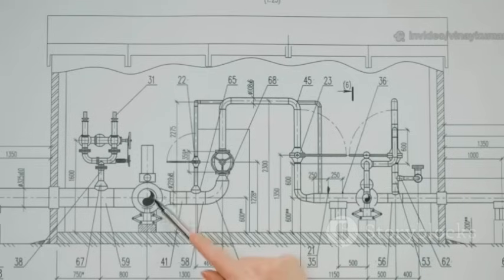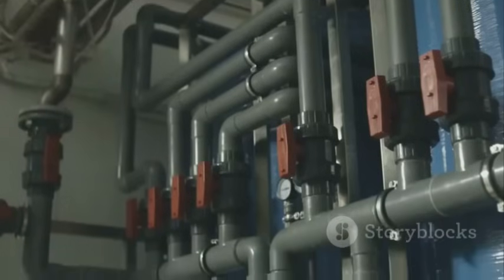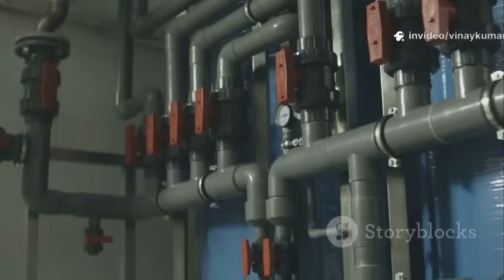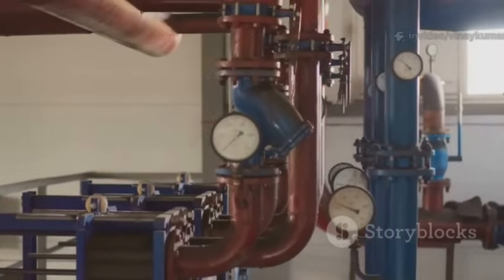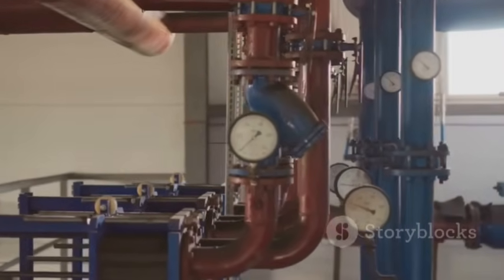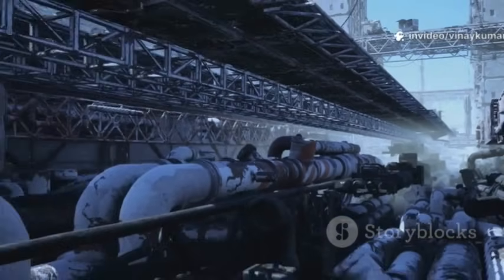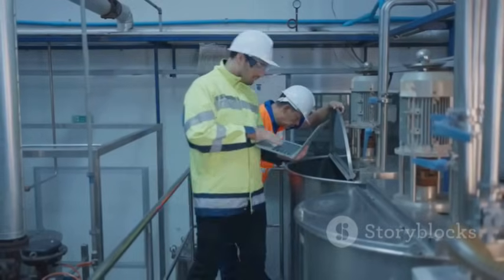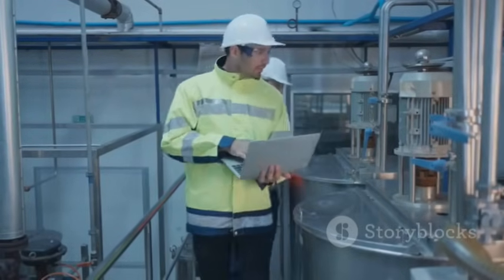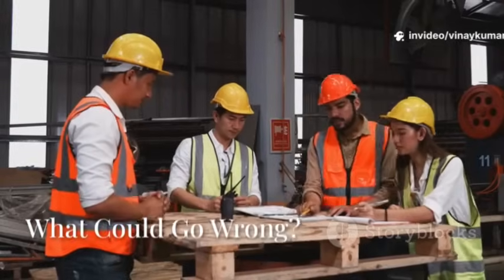Finally, you need detailed information about the equipment in the process. This includes materials of construction, piping and instrumentation diagrams, P&IDs, electrical classification, relief system design and its basis, ventilation system design, design codes and standards employed, and safety systems like interlocks and detection systems. It's the blueprint of your facility. Are the pipes made of a material that can withstand the corrosive chemical flowing through them? Is the relief valve sized correctly to prevent a vessel from overpressurizing? Having this information readily available is critical not just for safe operation, but for maintenance, troubleshooting, and any future modifications.